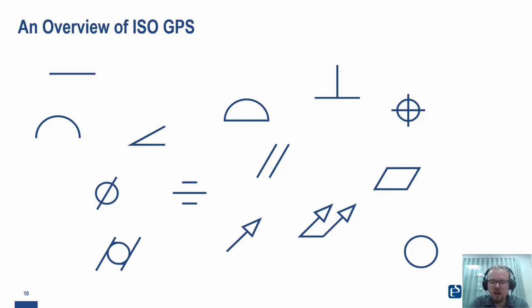For instance, you may have parts that are turned in one operation to aid with coaxiality. However, if ISO GPS is applied, you can specify exactly what you want on the drawing, including coaxiality. This is just one of the many benefits that you can learn about in our training courses and other ISO GPS content.